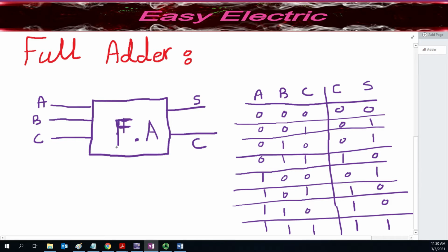For this lab project, with the gates, we are going to make one full adder and one half adder, first simulate them and verify these 2 tables, and make sure in simulation they work and our circuit is right. After simulation, we move to the TTL circuit and make the same circuits with TTL ICs and also verify these tables with the TTL ICs.